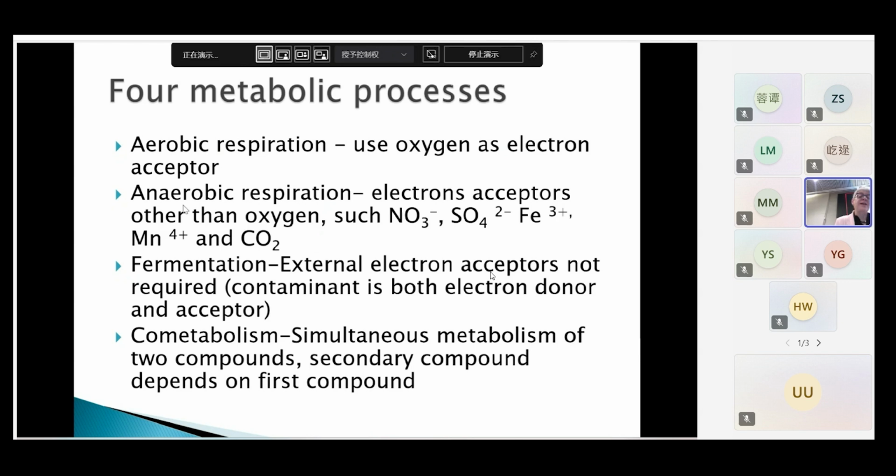Biosystems work pretty well. They tend to be less costly than other methods. You're not really generating any waste. Sometimes the permitting is a little bit more difficult, but again, it's the same procedures no matter what method you're going to use. You have to do the monitoring and make sure that things are going along as you expect. You could also do various processes ex situ. If you take out the soil, you could treat things as a slurry.